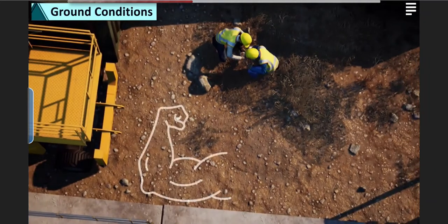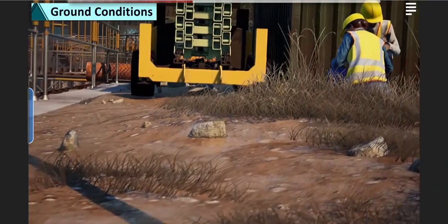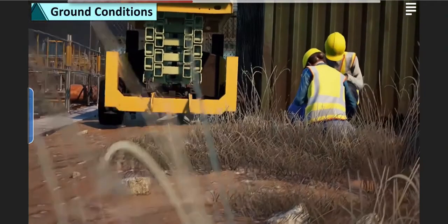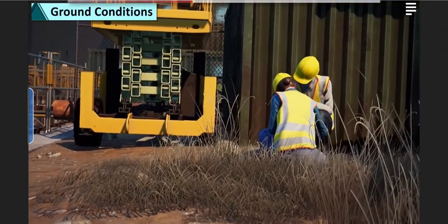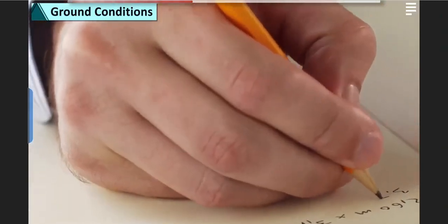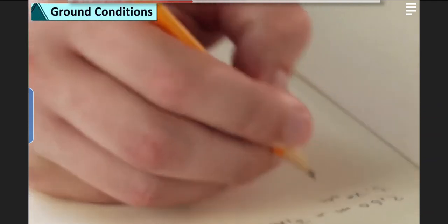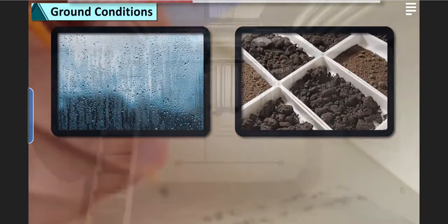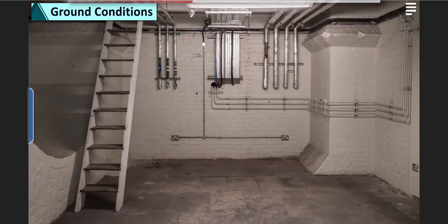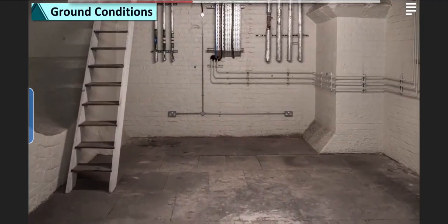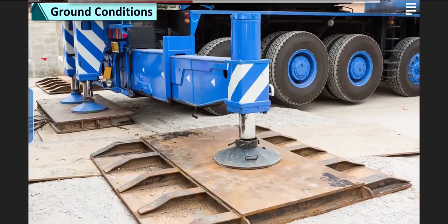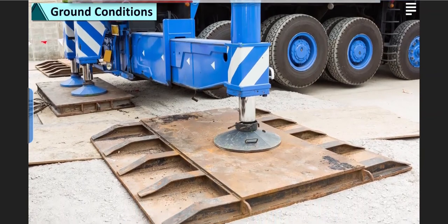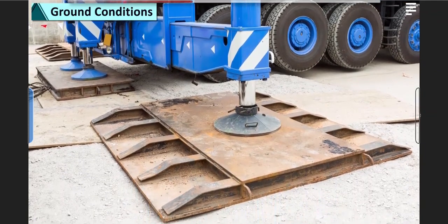This includes making sure the surface is strong and stable enough to support the weight of the MEWP and is properly prepared and maintained for safe MEWP operations. Surface strength and stability calculations must take into account surface material, soil type, moisture levels, and the presence of subsurface voids, such as cellars, basements, culverts, and pipes. Where necessary, foundations or spreader pads may be required to improve stability.